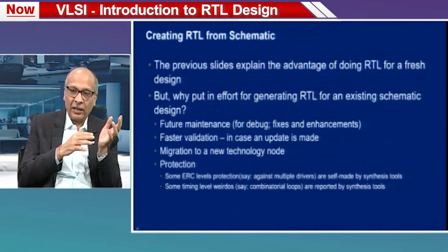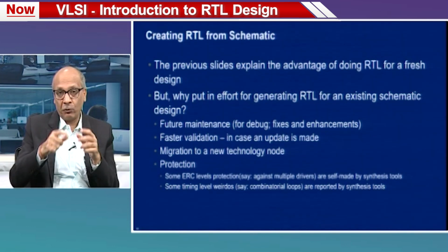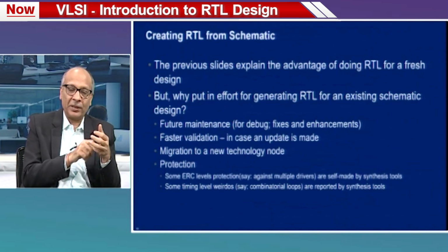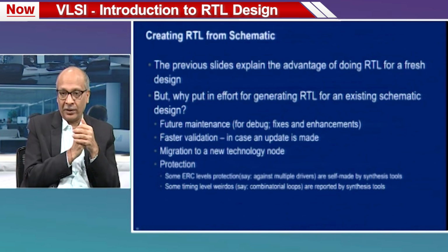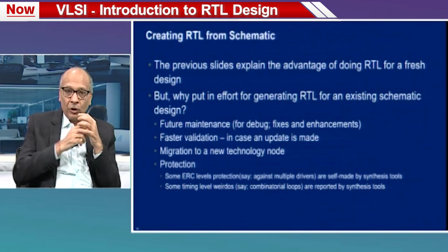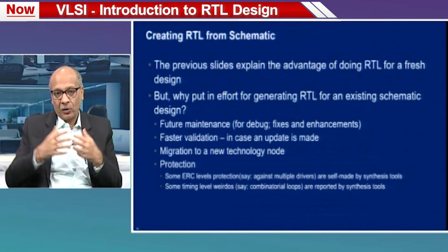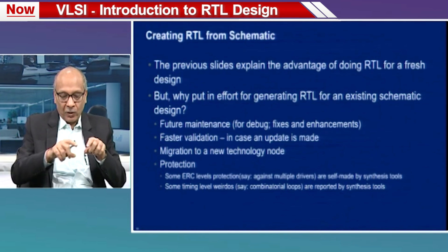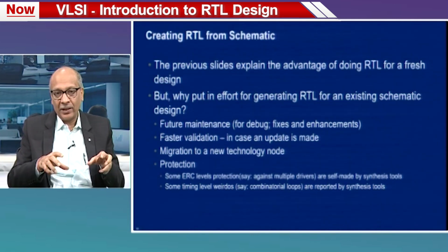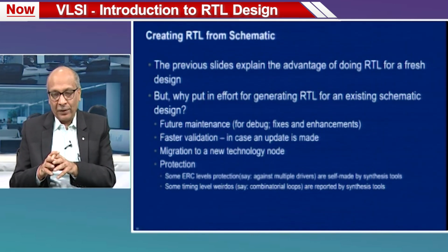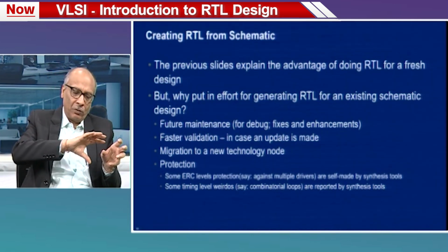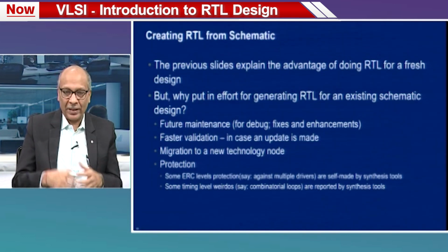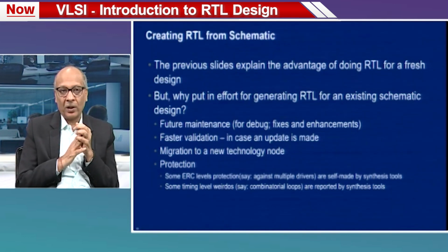Once you have the RTL, the validation will be faster. In case you want to make some updates, it is much easier to make the update in the RTL, and much easier and faster to validate in the RTL. If you want to migrate to a new technology node, say you were working on 28 nanometer and now you want to move to 20 nanometer, using a schematic-only design it is much more painful. But if you have an RTL, you have to run synthesis through the new library. So, migrating to a new technology node is also easy.